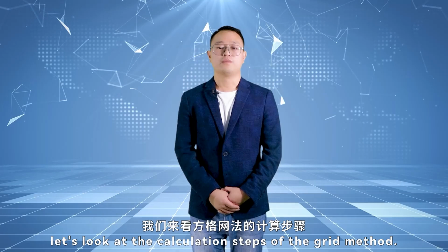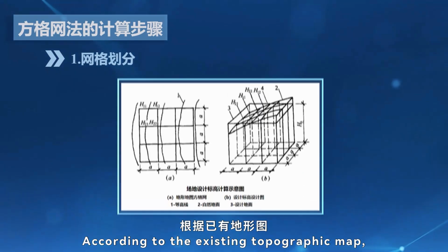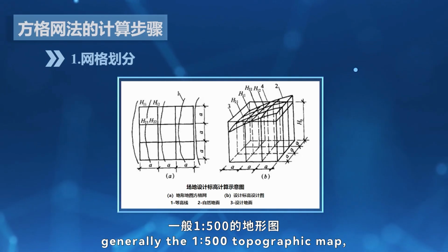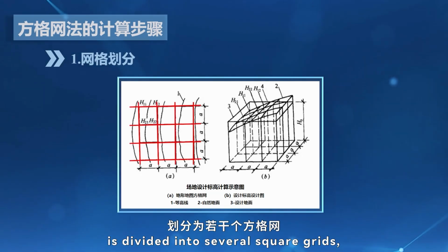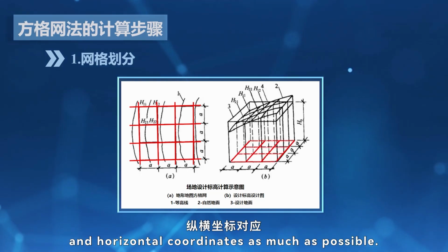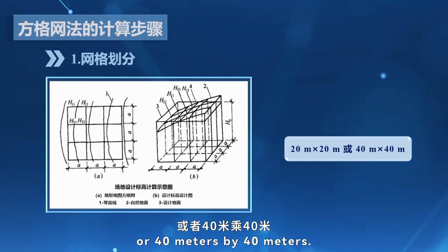Next, let's look at the calculation steps of the grid method. First, division of the grid. According to the existing topographic map, generally the 1 to 500 topographic map, the site to be calculated is divided into several square grids, which correspond to the measured vertical and horizontal coordinates as much as possible. The square grids are generally 20 meters by 20 meters or 40 meters by 40 meters.